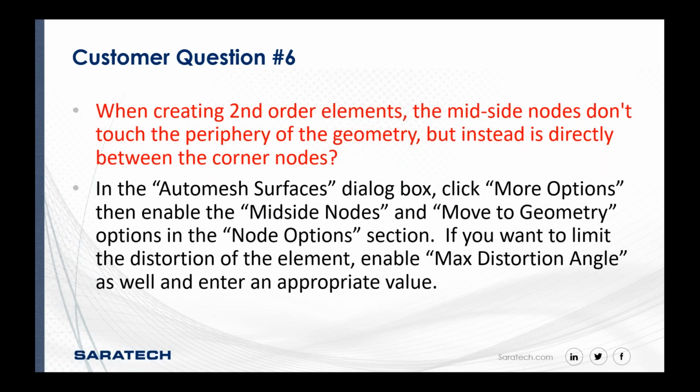Okay. Just another one here. When creating second order elements, parabolic elements, the side nodes don't touch the periphery of the geometry, but instead are directly between the corner nodes.